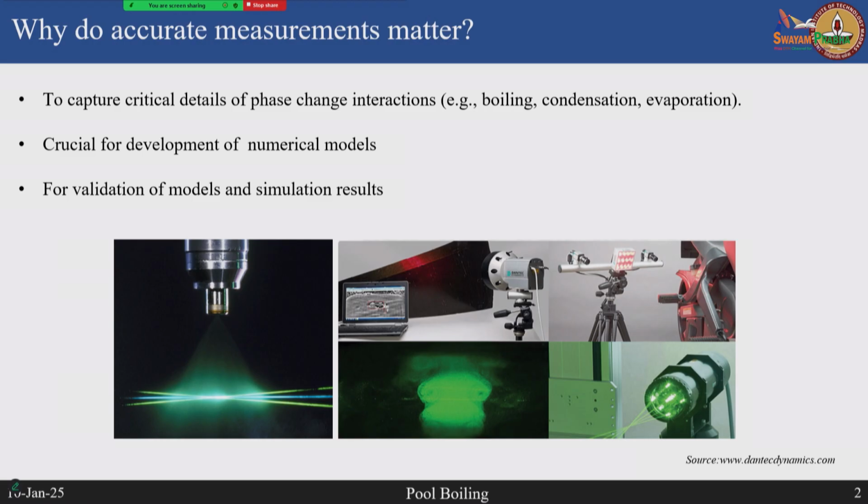But if you want to study the heater surface, for example how the distribution of temperature is and things like that, then simply using thermocouples may not be adequate. Then you have to use some non-invasive techniques like infrared thermography. For temperature measurements which are non-contact and non-invasive, infrared thermography is one of the state of the art techniques that people have been trying out.